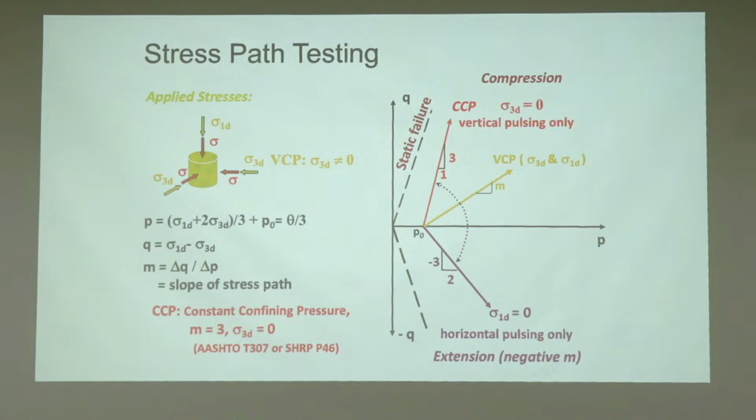Right? So you actually install pressure sensors and measure that, okay, this is what I am seeing for my aggregate in terms of sensors. So now you calculate P and Q really, and then you go to this advanced triaxial and program it so that it does the exact same repetition. Then you can have a better simulation of what is happening in the field.